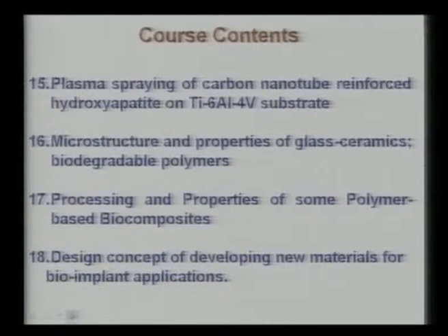The materials aspect means how these glass ceramics are prepared by conventional heat treatment as well as spark plasma sintering, and how their properties will vary depending on the content of the crystalline ceramic phase in this glass matrix. Now, the next material class that will be dealt with in these lectures is the polymer based biocomposites